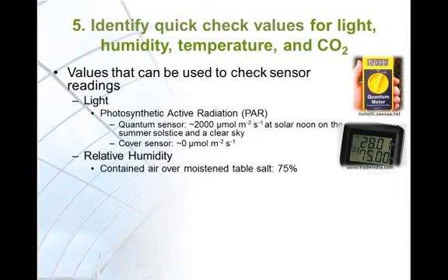The saturated salt solution, made up as a slushy mixture with distilled water and chemically pure salt, is enclosed in a sealed metal or glass chamber. Greenspan identified the relative humidity of air over a saturated table salt or sodium chloride solution at about 75%. When there is a heavy mist outside, the relative humidity is about 100%.